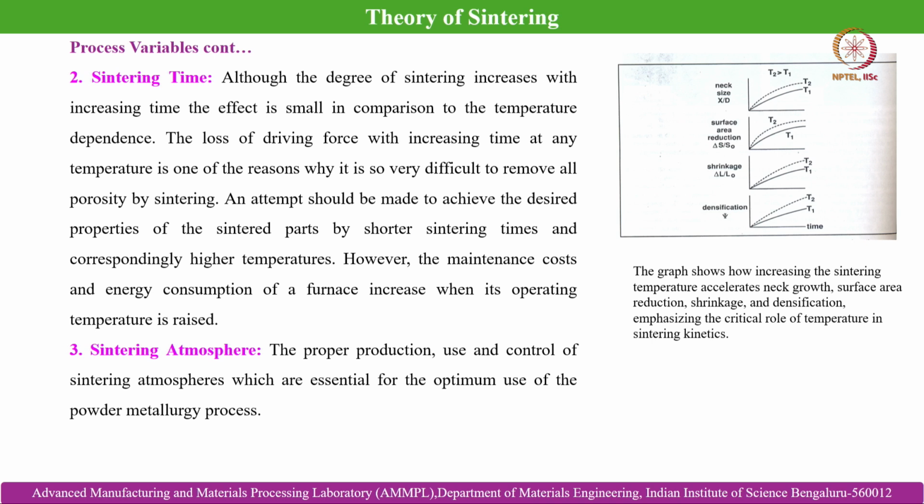However, the maintenance costs and energy consumption of a furnace increase when its operating temperature is raised. So that is what I mean. We need to deal with multiple situations here. I can start by drawing a sintering cycle, although I have drawn it earlier, but I am drawing it again for your ease of understanding. This is a typical example of alumina, where the sintering temperature is generally considered as 1600 degrees centigrade.